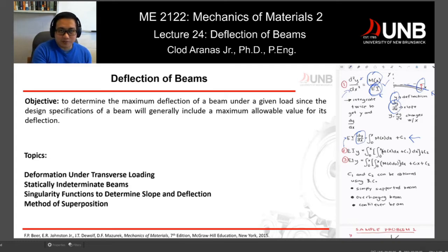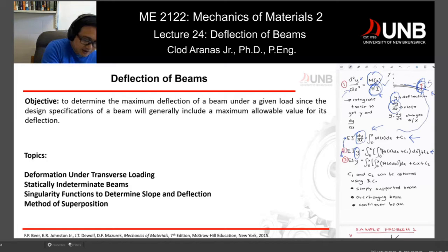Now, it's not just about how it bends, how much deflection you get from your reference point. So you can further integrate this equation here. And once you integrate this one, you will get this second equation right here below. So again, this number 2 here should be on the top because this 2 and 3, they are the same. So once you integrate it, you are left with just y. And y is your deflection going back to your beam right there. The x is just the x-axis. This part right here would be your y, which is your deflection.